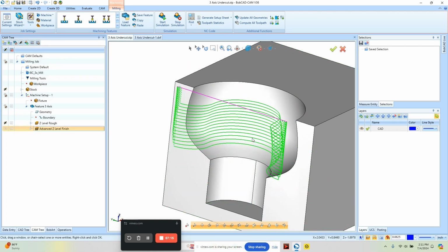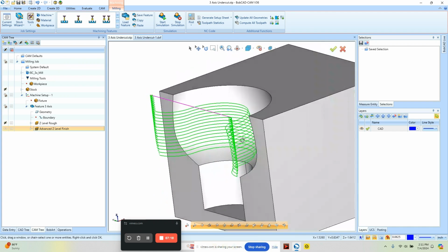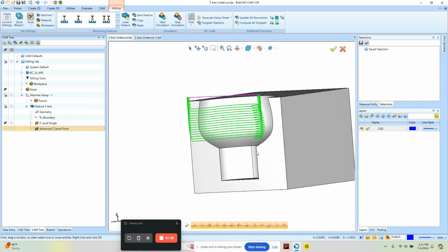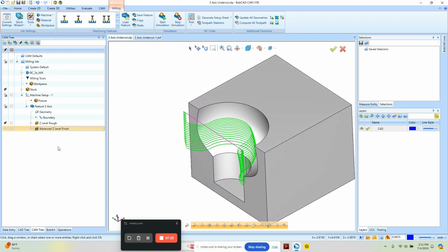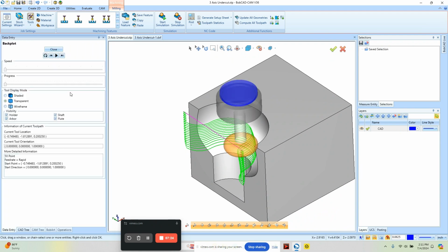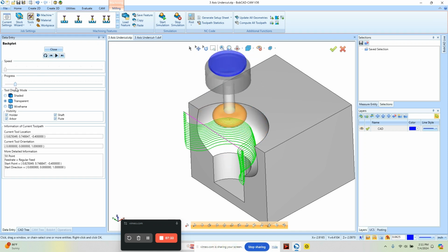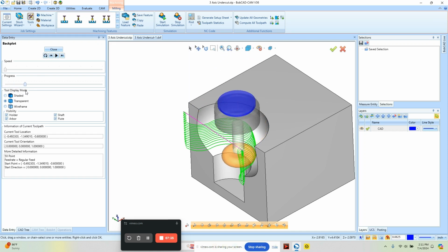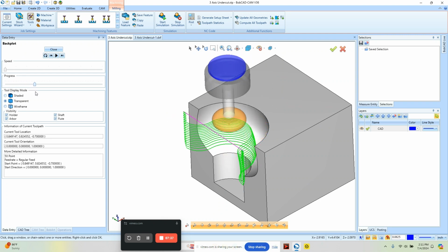Alright, you can see the tool path work its way to come in here and to cut this shape. Because it's an open shape, you can see it's coming in from the outside. It does kind of roll over the edge, which we may or may not want, but this will come in there and machine that area and then work its way back.